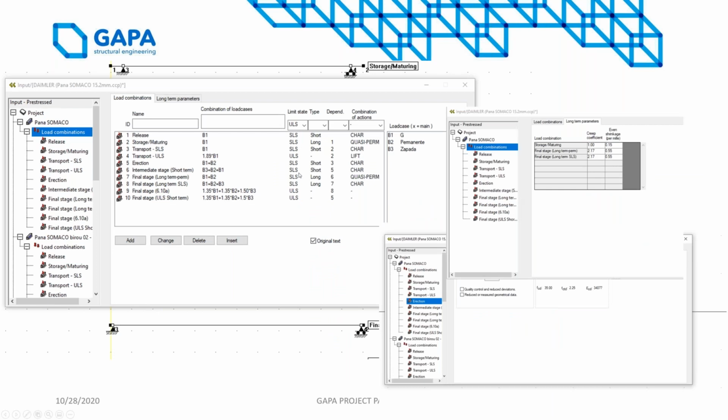Right. After defining the sections and the reinforcement, the design process continues with load combinations, definition, and load input. For each loading situation, a different concrete strength class can be used, thus simulating the concrete hardening process. This is an exercise that would be very laborious without the use of a tool such as prestress. So it was quite difficult for us to do this in Excel and still keep a manageable spreadsheet.